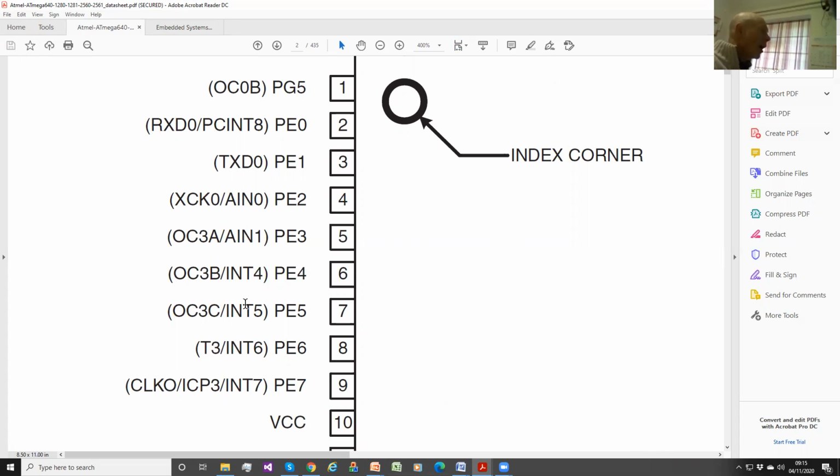Most robots have 6 or so axes maximum. So you could make a robot with 6 servos controlled directly from the microcontroller without any shortage of pins. But the important thing to realize here is one timer can actually have more than one of these output compare signals, and also that the output compare signal is just on a pin like any other signal on the microcontroller. There's nothing particularly special about this pin.